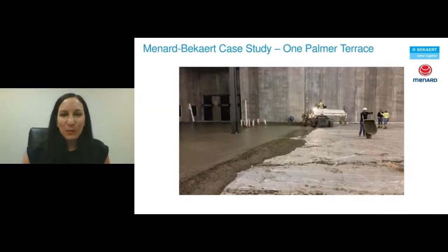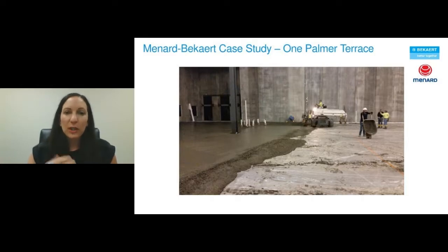And this is what it looks like, right? When you construct a floor like this, it basically looks like a slab on grade. You come in and do your soil improvement work, you lay your slip sheets, you can then use a laser screed. So a lot of these projects now, especially with the higher floor flatness and levelness requirements, the use of a laser screed can certainly help you achieve that, and a fiber solution can help make the use of a laser screed possible.